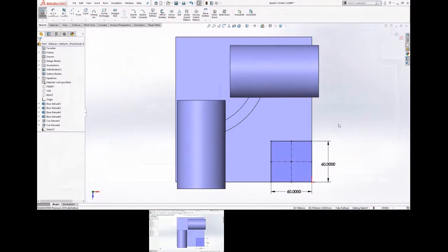The reason why, and I may get this wrong, I have to remember we've done it both ways. In the next iteration, this boss gets removed and that pocket extends out. So when you suppress that boss, the pocket explodes, obviously, because part of the geometry is gone, the offset geometry. And when you go in to edit the sketch, because of the way the fillet was created, it's just unrecoverable. You end up having to wipe out the entire sketch and start from scratch. So I'm trying to remember the way I did it this morning at Starbucks. I think I'm going to do it as a feature, because I believe that's the way I did it this morning. This is basically 10 millimeters above that face.